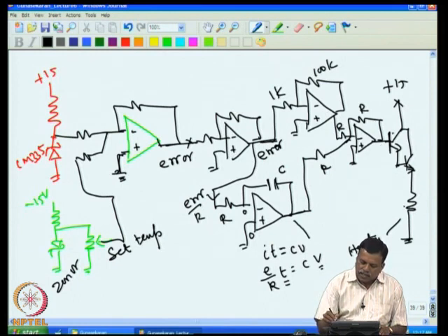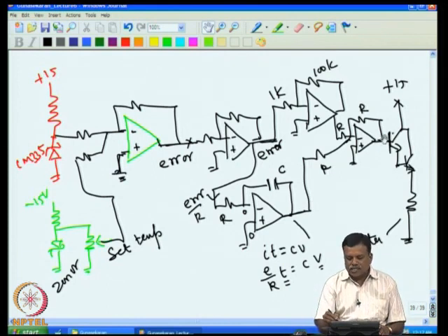That is anyway minus, and that becomes plus, and the heater will be driven. At that time the capacitor was not charged, so you will have almost zero voltage, but since the error is there, it will slowly start increasing towards the minus side, and that will move towards the plus side. If it is already saturated, there won't be any change, but as this increases, this voltage is also supposed to increase if it is not saturated. Even if it is saturated, there is no harm.